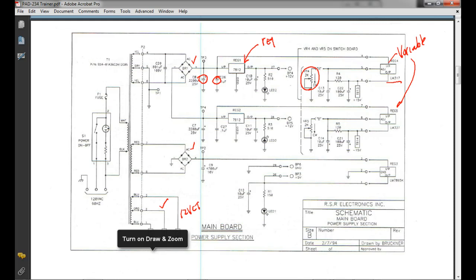So that's a lot of electronics in there, guys. You still only need unregulated in. So on the adjustable, you need unregulated in, regulated out, and then the third lead's called the adjust lead. So notice this lead is the one that goes through the resistors.